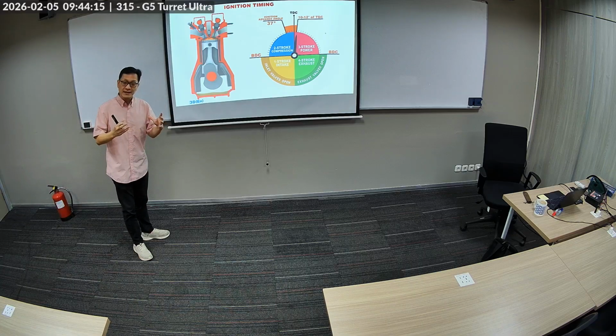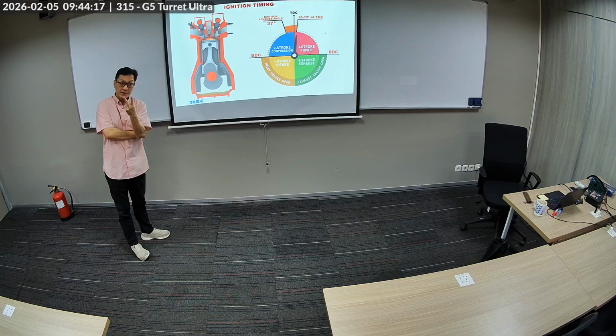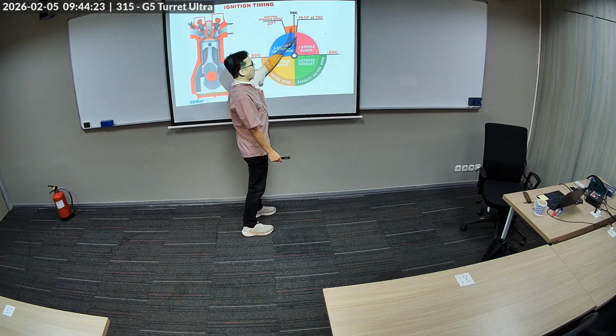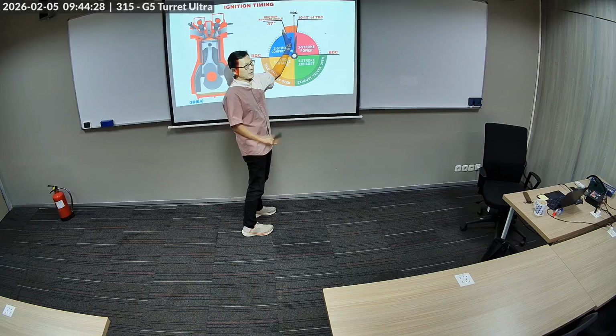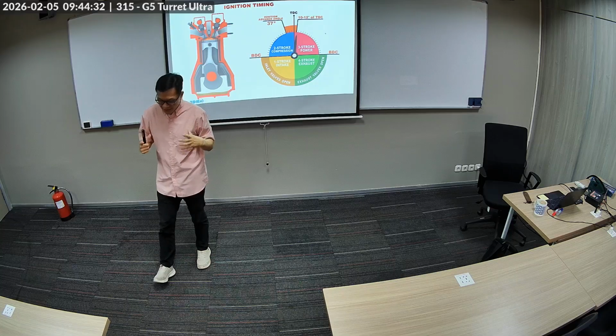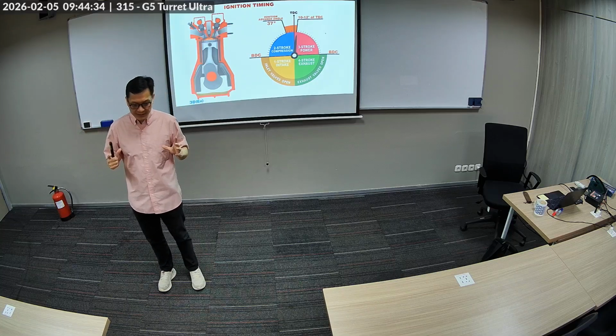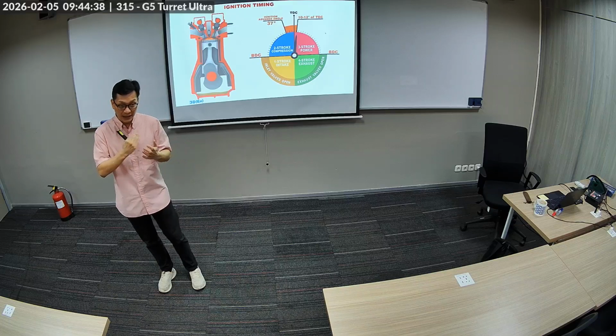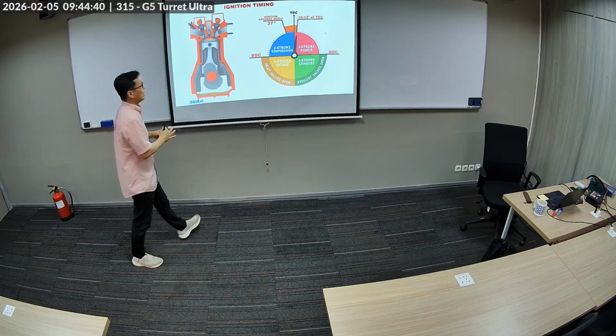And your ECU basically has two main tables, fuel and ignition. This is based on RPM, obviously. Higher RPM, then you have to start early. But this table in your ECU is like an Excel table, basically. It is the adjustments that you can make for each RPM and each engine load.